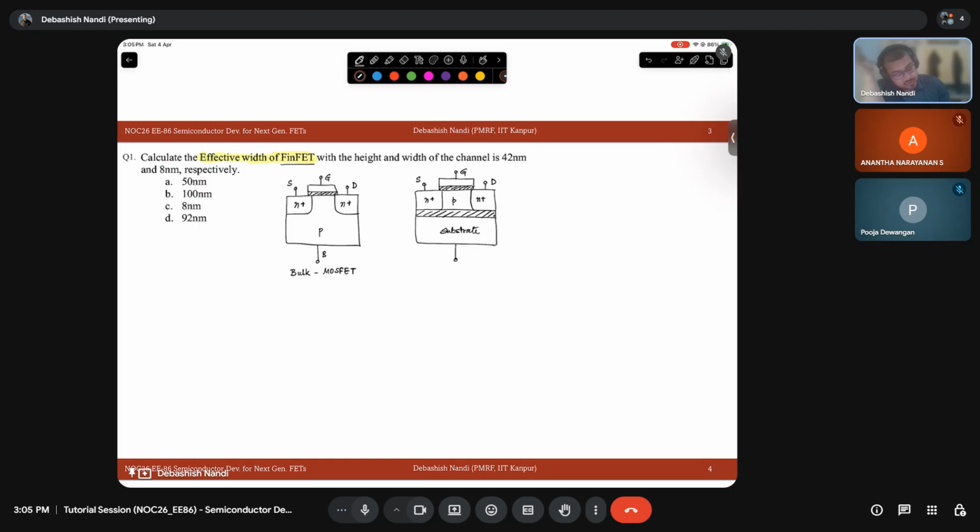This is source. So what is this structure called? This is called silicon on insulator MOSFET, right? So note that this is my single gate structure. This is my double gate structure, right? This substrate terminal can also act like a back gate because I can have field effect from this side as well. It is just like two MOS structures joined together.